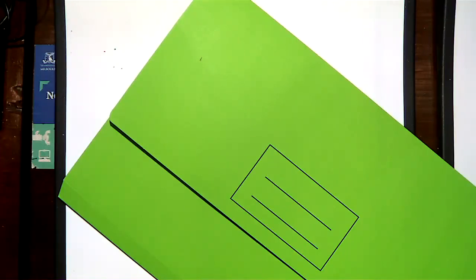So therefore, what you've got is C1, 2, C2, right? So you've saved yourself the capacitance. So therefore, by doing this trick, your circuit runs much faster, right? And it's a layout trick, right? And that's why I was trying to emphasise it's a layout trick, and that's why I've got half the capacitance.